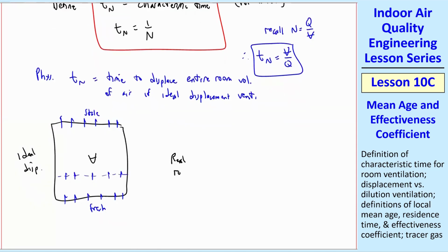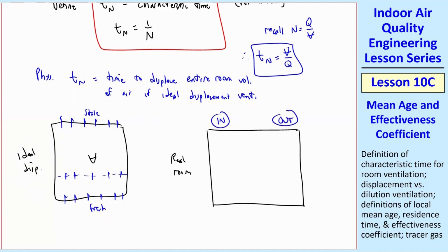A real room would be nothing like that. Some clean rooms come close to that. But a real room in the USA, we typically have some inlet or supply and some outlet. These are typically both in the ceiling. I'm sitting in my office, and that's what I see here. I have a supply coming in one location and an exhaust coming out at a different location, both in the room. So that's pretty typical. And you have a diffuser to push this around instead of just coming straight down. And then it's sucking out air through the exhaust like that.